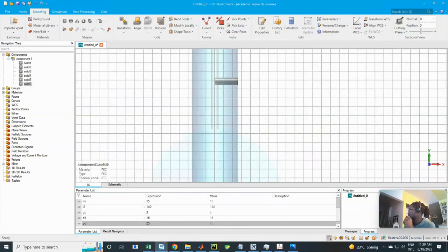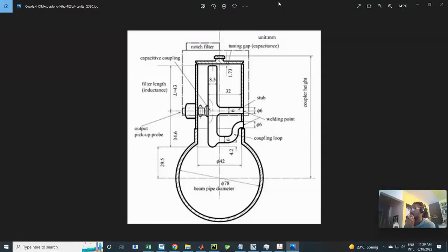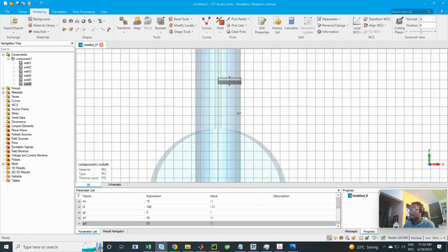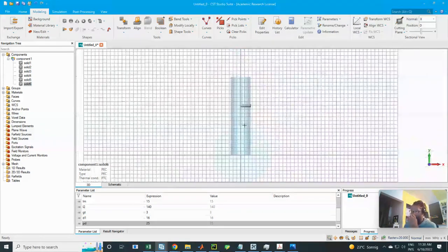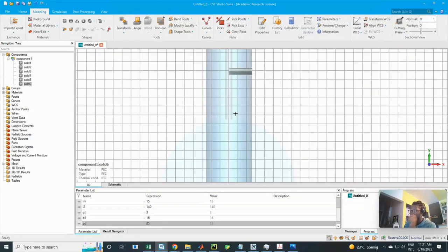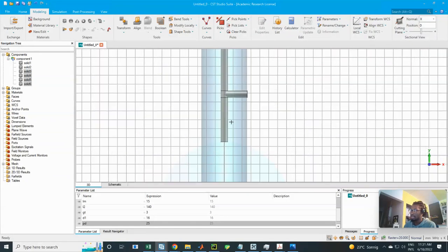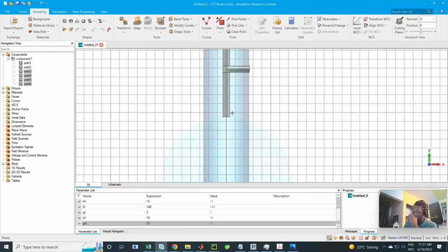Then for the notch part of it, which is this, I'm going to be using a sweep operation. I'm going to be using a sweep, and we're going to start with a sketch. This is what we have. And if you notice, I haven't performed any boolean operation on it. I usually like leaving it that way until I'm done with the entire geometry.